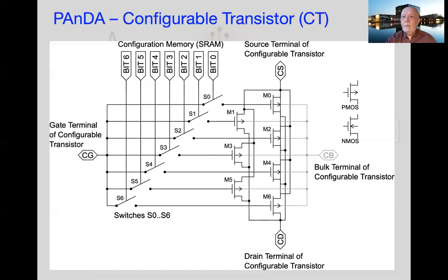So if you connected two 10 nanometer gate transistors together, they would effectively have a gate width of 20 nanometers. And what we saw in a previous lecture, in lecture 2, was that by changing the functional size of how the gate is built up, it changes the characteristics of our transistors.